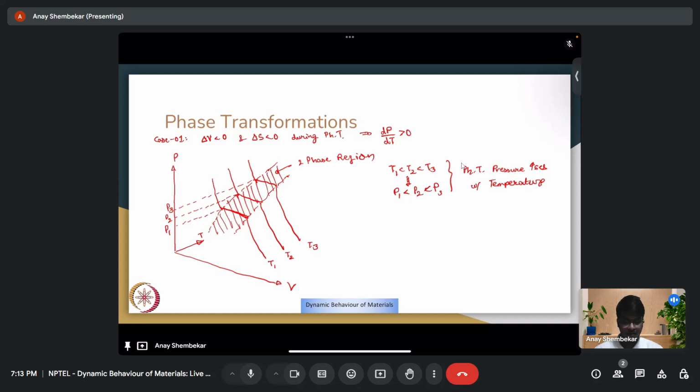What we are interested in is trying to see how the Rankine-Hugoniot curve looks. Remember that the shock wave is passing through the material in a very short duration of time, which means whatever energy dissipation occurs, it doesn't have a lot of time to move away from the shocked region.